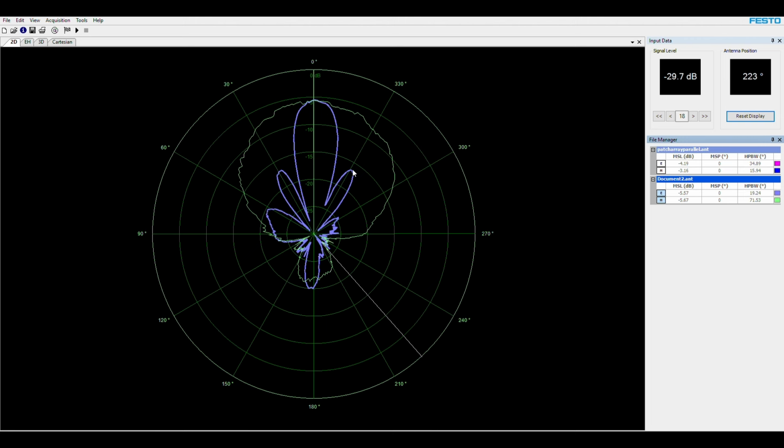The other thing that you notice here is that these two lobes in the E-planes are not symmetric. Can you justify that? See what could be a possible reason for that, or if you think that's a measurement error, you can also indicate that. And remember, these two things were when we are almost at 90 degrees, so we are looking from side toward the transmitting antenna. So yeah, that's essentially our E plane and H plane.